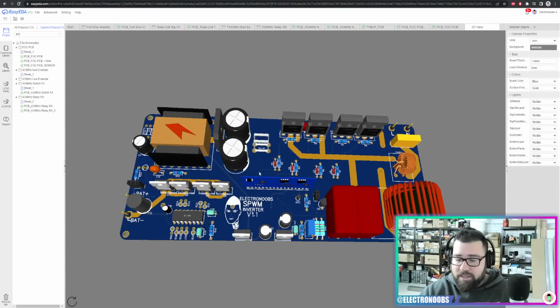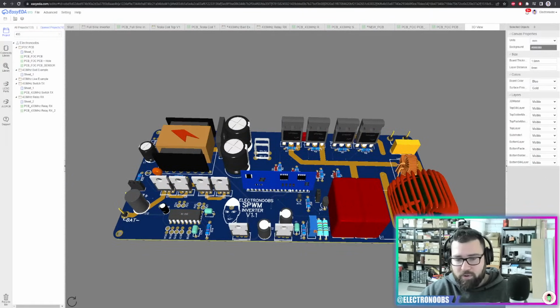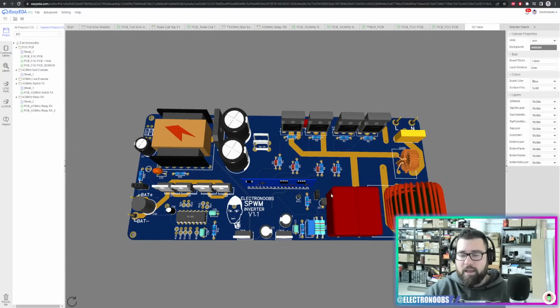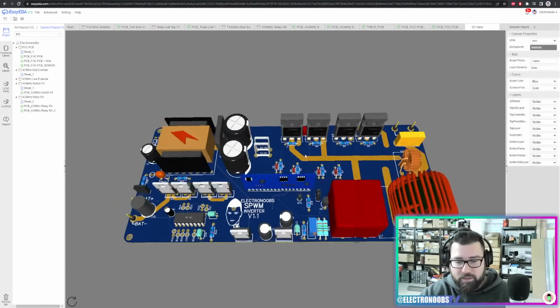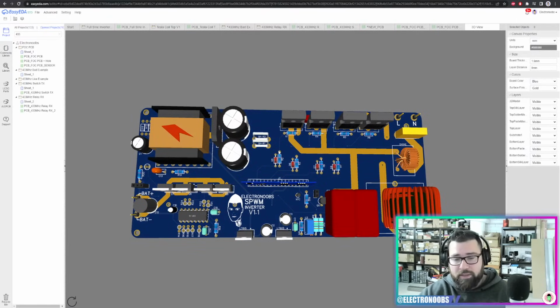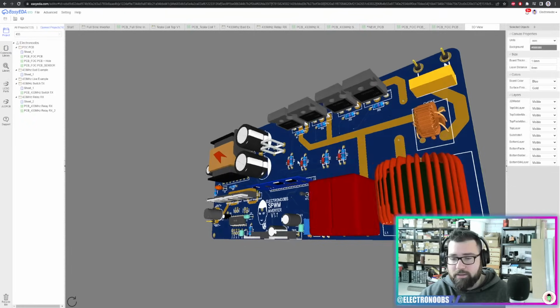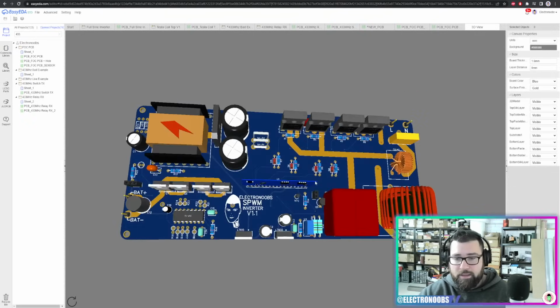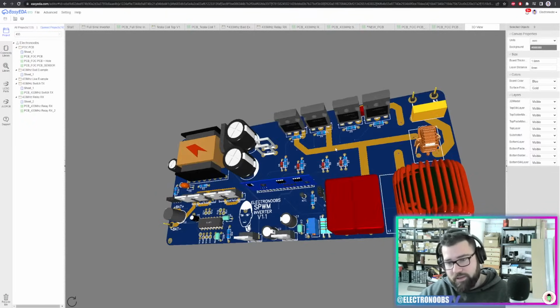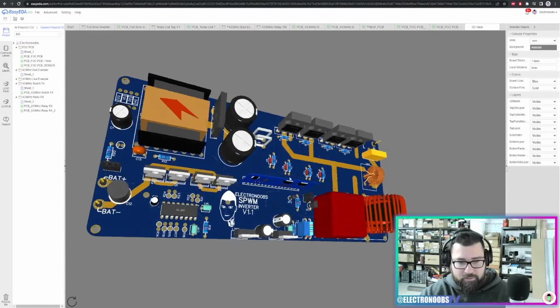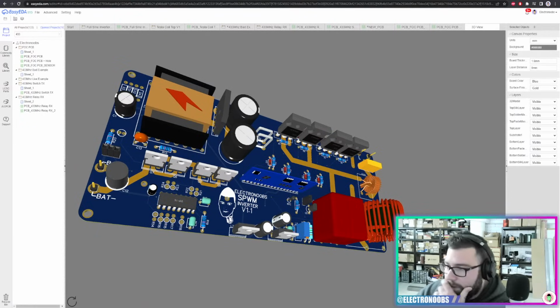The decoupling capacitors should be as close as possible to the driver, because anytime it needs power or has a voltage spike, you need that capacitor very close to the driver, so it will keep the voltage supply very stable. What other things should I tell you? The tracks should be at 45 degrees. The exposed copper is very dangerous because you could touch it. What other stuff can I tell you?